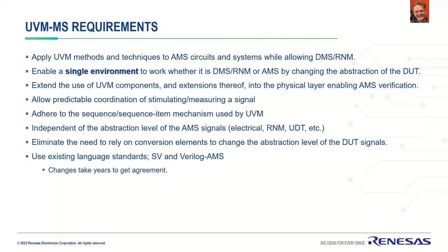As I said before, the concept is to apply UVM methods and techniques to AMS circuits, whilst allowing DMS and real number modeling to enable a single test bench environment to work, whether it's using any of those abstractions of the DUT, and to be able to describe a methodology which takes existing digital UVM components and allows you to readily extend them with the minimum of fuss to then use with the mixed signal physical layer.